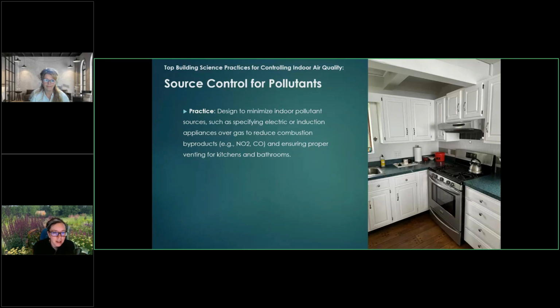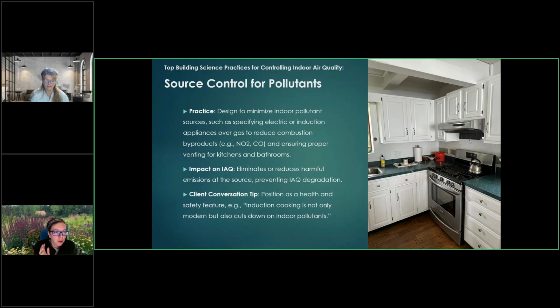Practice is to design to minimize indoor pollutant sources, such as specifying electric or induction over gas. The tighter we build our homes, the scarier gas ranges are, and ensure proper ventilation for kitchens and bathrooms. Eliminate or reduce harmful emissions at the source by preventing IAQ degradation, and position as health and safety features such as induction cooking is not only modern, but it also cuts down on indoor pollutants. And a lot of home chefs actually really like induction because it can be fine-tuned.